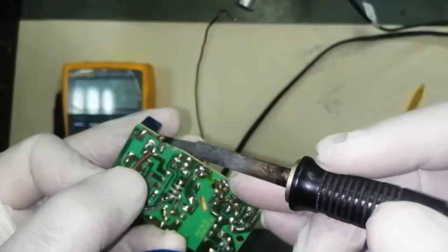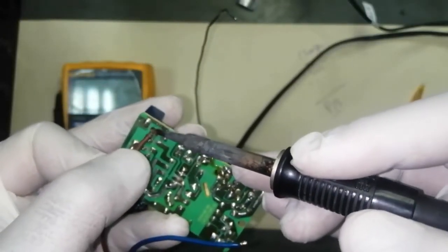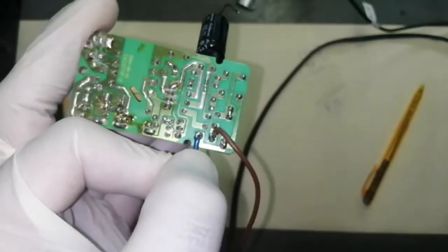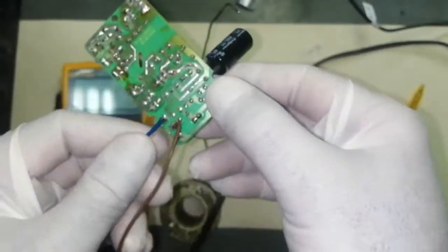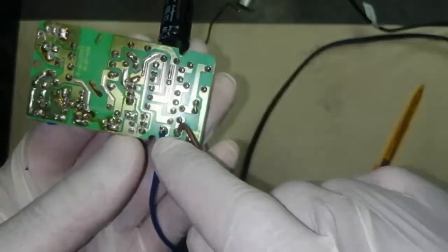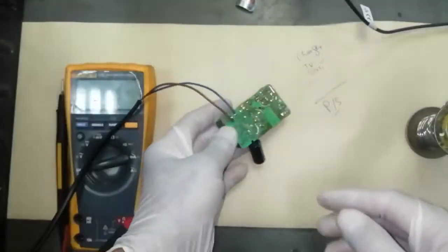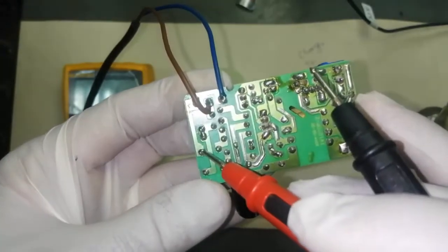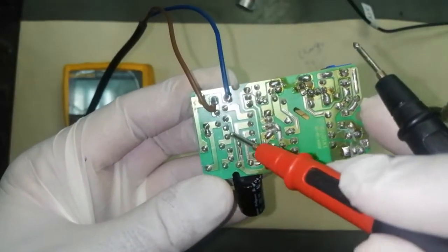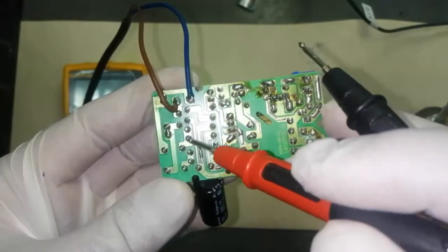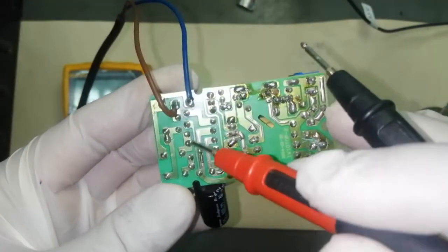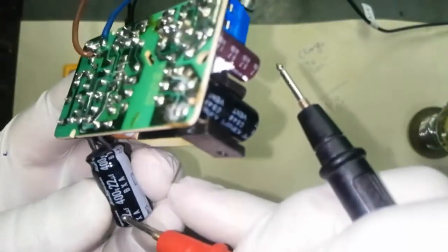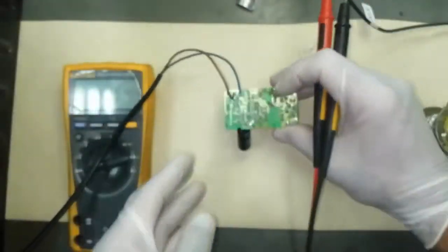So I will connect the one line which is the input terminal for AC, and when you are making connections, don't make any loose connection or long lines. Connect power. What we will do is check the voltage here, AC voltage. Here we will find AC voltage, after the capacitor AC voltage, at the bridge rectifier. These two lines are for the bridge rectifier. Until here we will check AC voltage. After that, at the capacitor we will find about 300 plus volt DC.